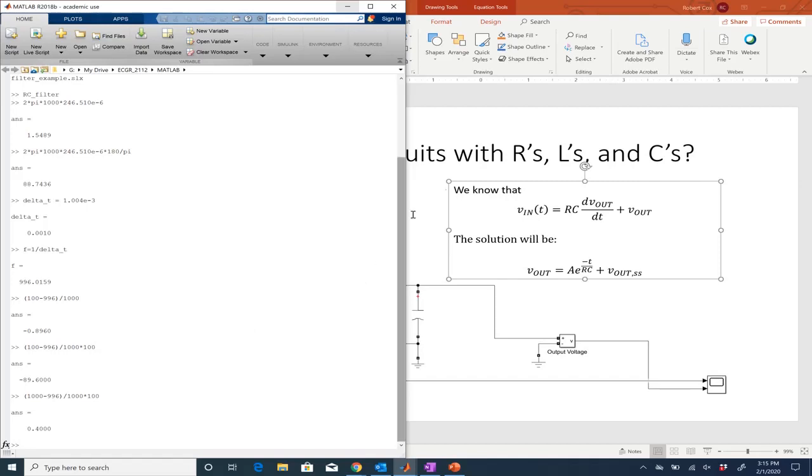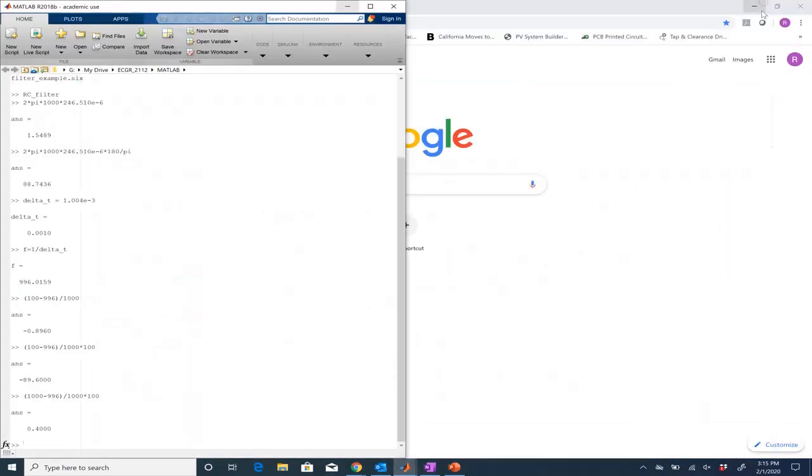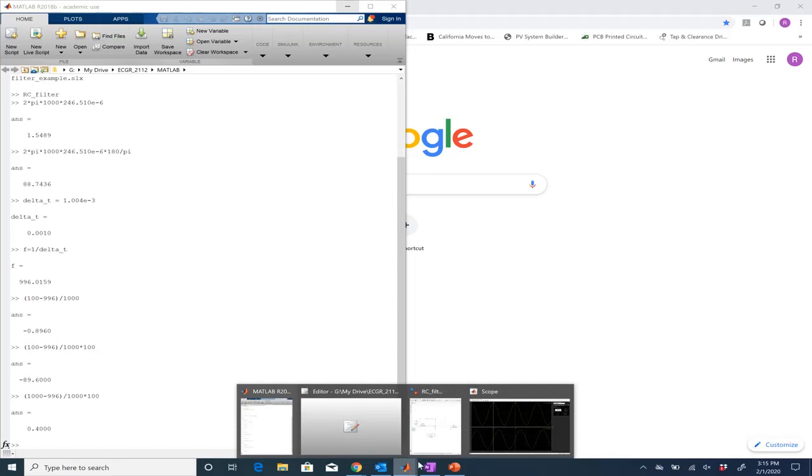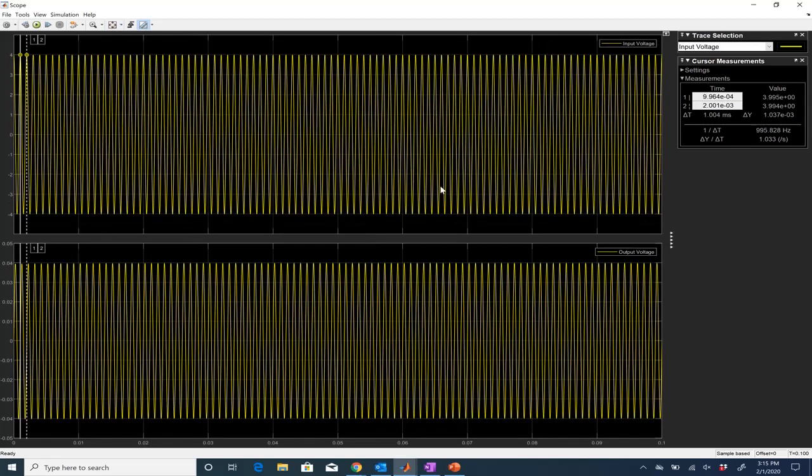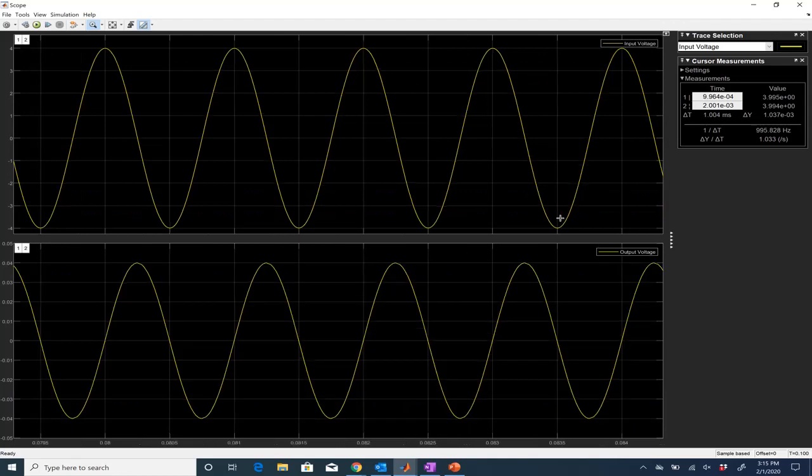All right, that's a pretty small error that I just had from my measurement. Now let's say what I wanted to do is figure out the time between these waveforms. So I'm going to zoom out a little bit. Now I'm going to choose my magnifying glass, and I am going to zoom in somewhere out here where I know I'm truly in steady state.